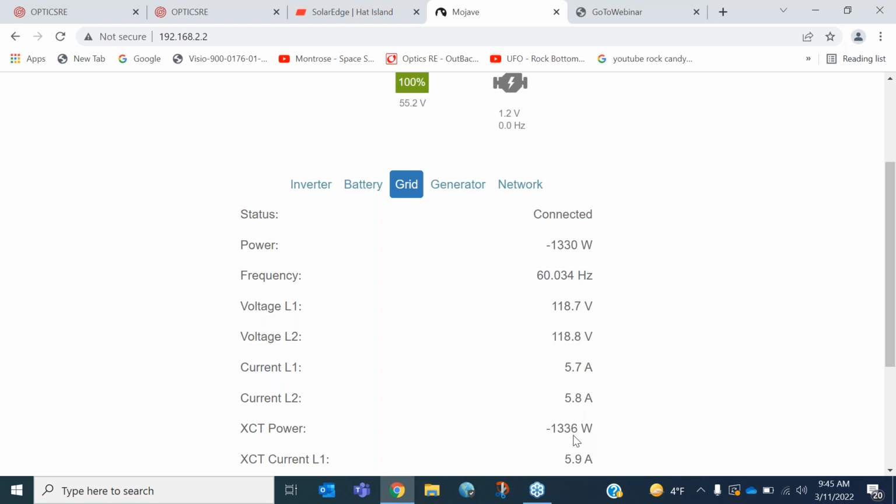So that was just kind of what I wanted to show. You can see the support function where it says don't allow more than this in. Time of use does exactly the same thing, except it automatically sets the import to 0, so nothing comes in during these time frames. And the nice thing about it is you can set your battery current, don't allow more than this. Take it down to this level.